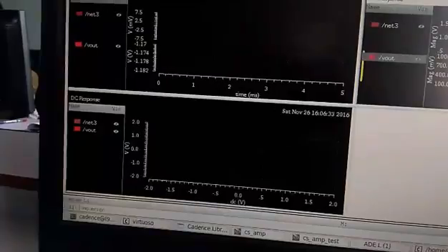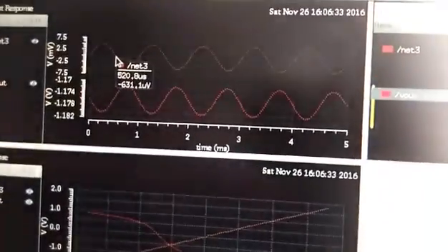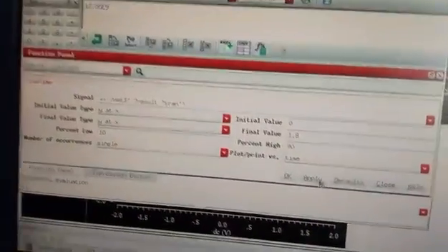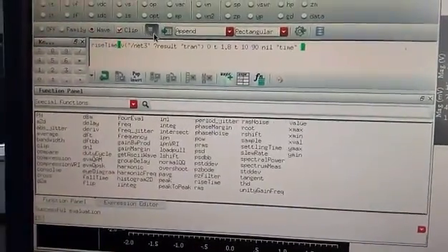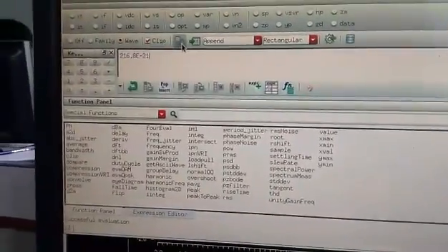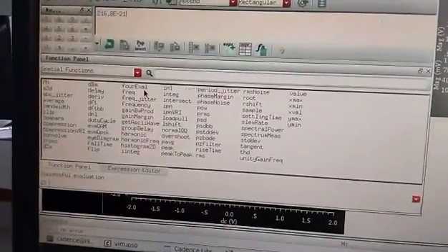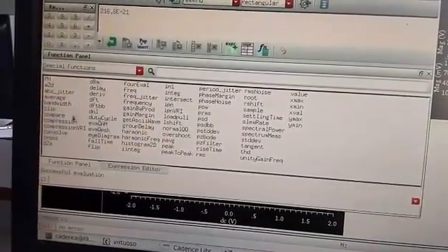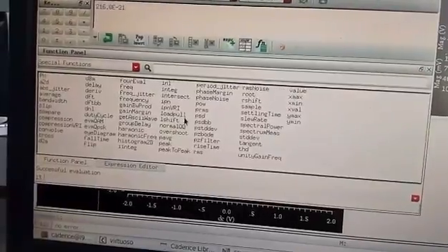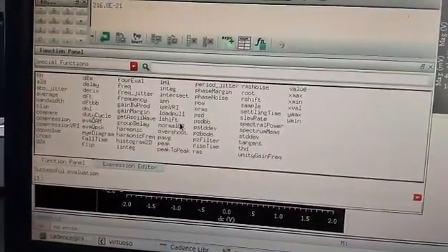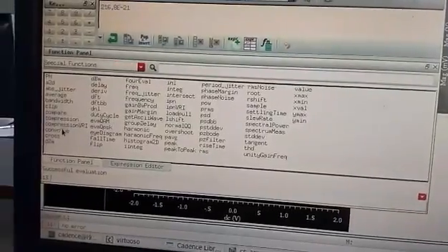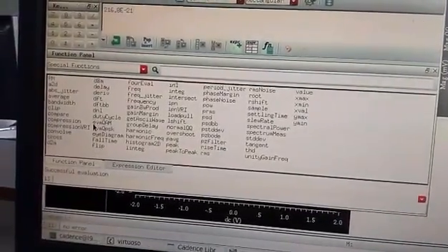Here we're calculating the rise time. Yes, we'll be clicking on the rise time, apply. Okay, now run. Yes, we got it. We can also calculate the fall time in the same way. I'm actually thinking, is the rise time and fall time needed for a CS amplifier? If yes, then cool. If no, sorry, I added it.